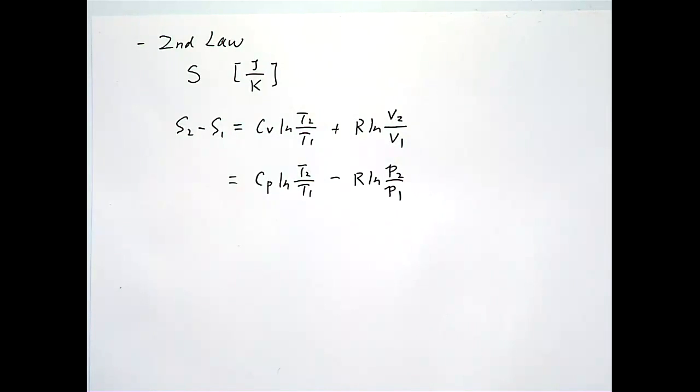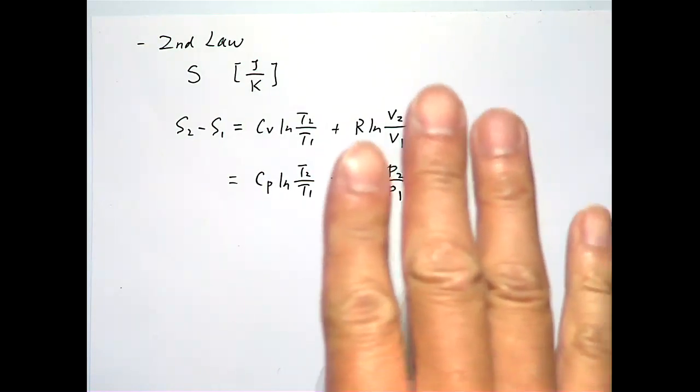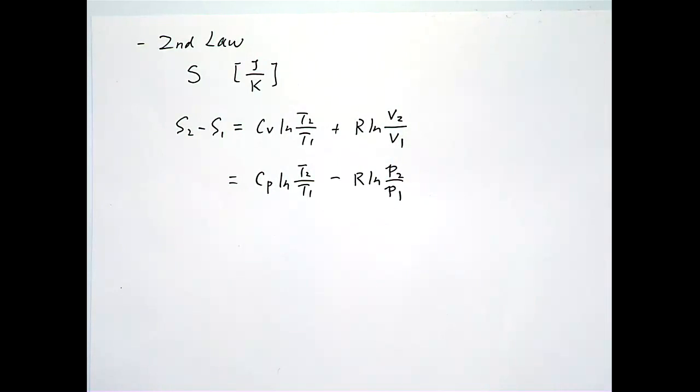The purpose of deriving the Gibbs equation is so we can calculate the change of entropy from one state to the other. When we derived the Gibbs equation, if you recall, we started from a closed system going through a reversible process. People later realized that this equation is actually more universal. It can apply to irreversible processes as well as open systems. So the Gibbs equation is a universal way to calculate the entropy change.